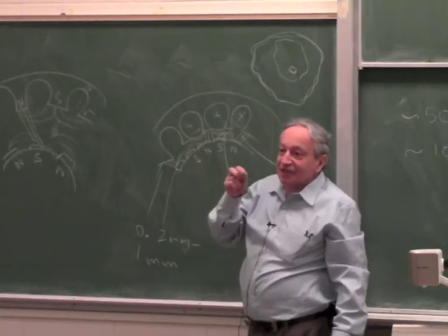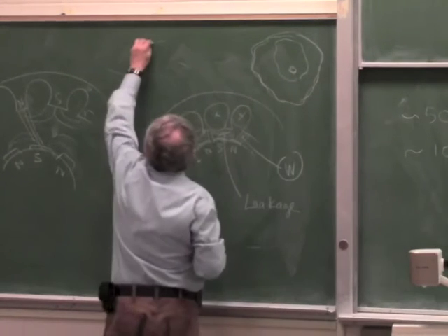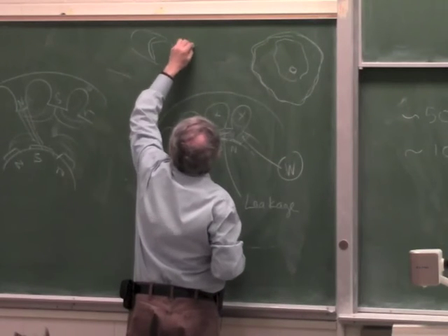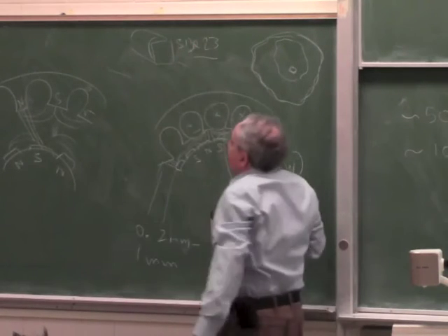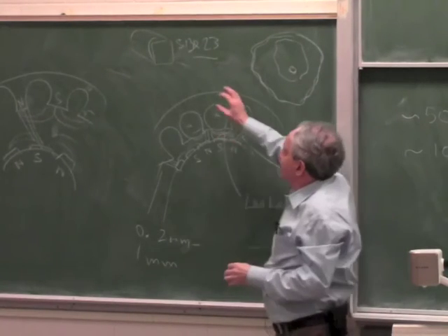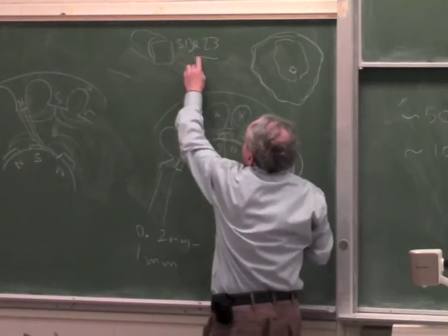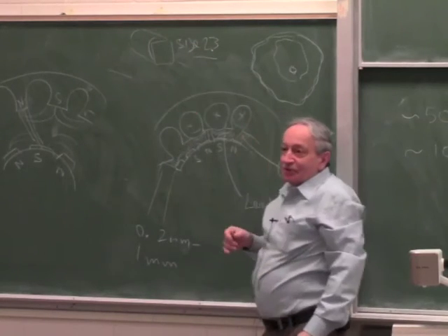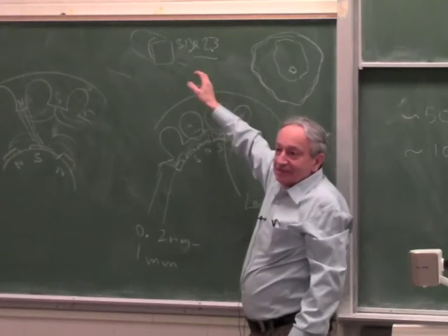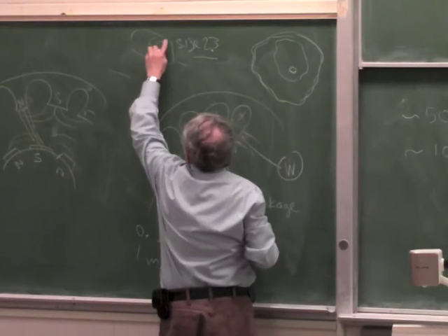But think of the other thing. In a normal stepper motor, the standard size that is most popular is called size 23. I don't know if you know, all motors have a frame size, and the frame size is a diameter in inches. That's kind of an old standard. Size 23 means 2.3 inches. So almost all the motors you have in your lab are called size 23, right? So it's 2.3 inches. Anyways, that's about 60 millimeter.